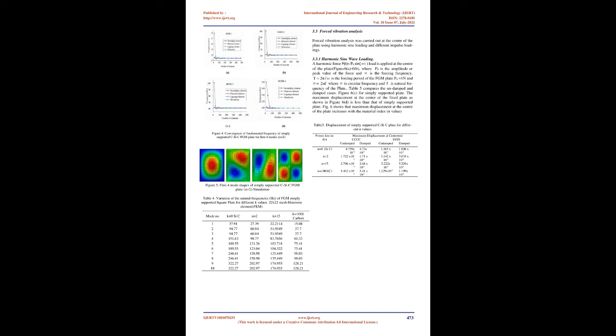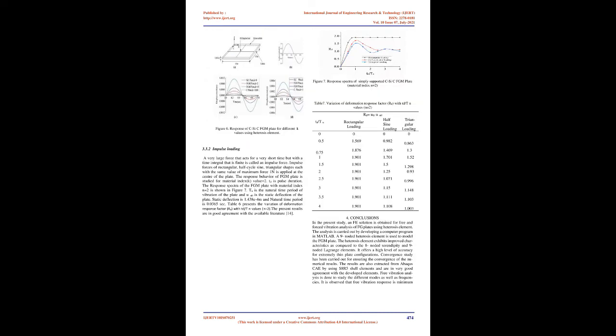3.2 Free vibration analysis of C-SiC plate. The analysis is done for a C-SiC plate, 0.5 x 0.5 x 0.001 m. Material properties are given in Table 3. Convergence results are shown in Figure 4. The first 4 modes of vibration are shown in Figure 5 by Abaqus using S8R5 shell element. Frequency of vibration is minimum for carbon plate as shown in Table 4.